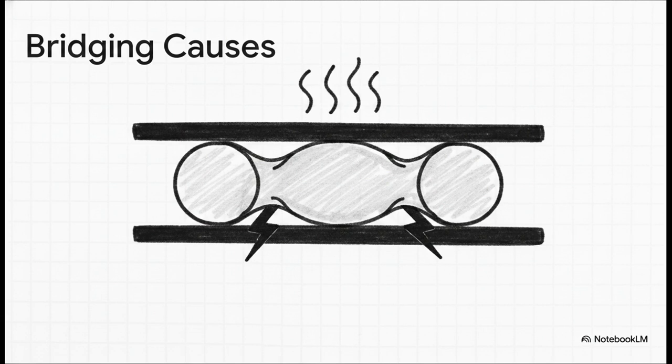When the metal is liquid, too much solder volume can cause it to bulge out laterally, or dynamic package warpage, or even just a slight misalignment during the delicate pick-and-place process literally squishes adjacent solder joints together. And once they touch and cool, bam, your chip is short-circuited.